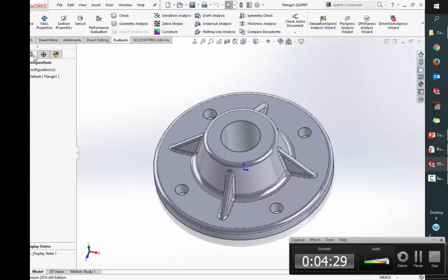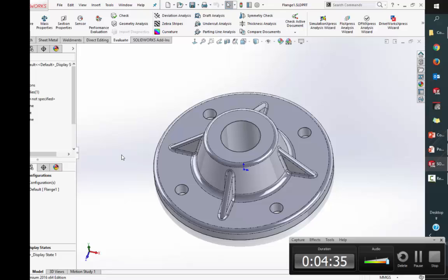One of the little secrets inside of SOLIDWORKS is that the little bar with the dot on top of it is actually a way to split the tree here. So you can see your features above and your configuration manager below. It's one of those little things you kind of see in there. When I'm dealing with configurations, I end up flipping tabs quite a bit. This gets rid of that because I can show the different variations right there.